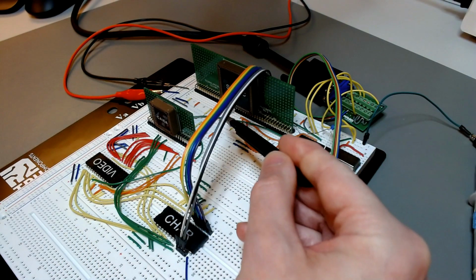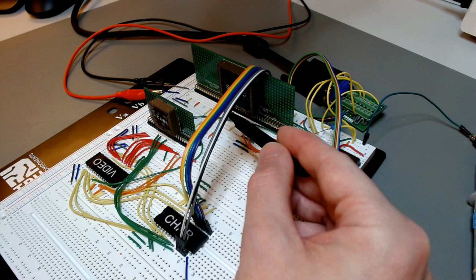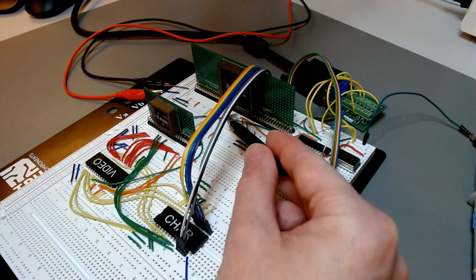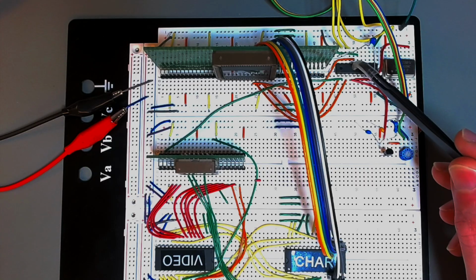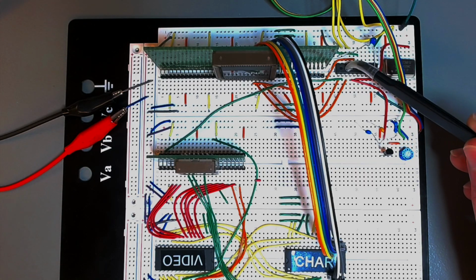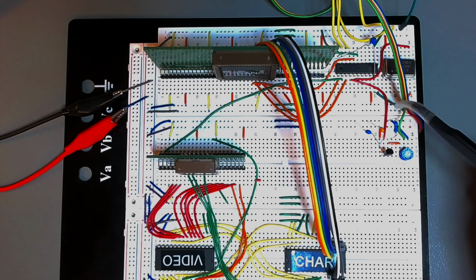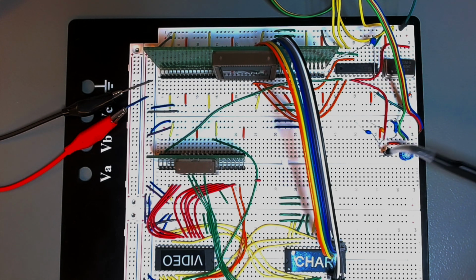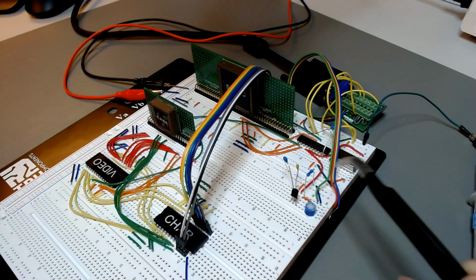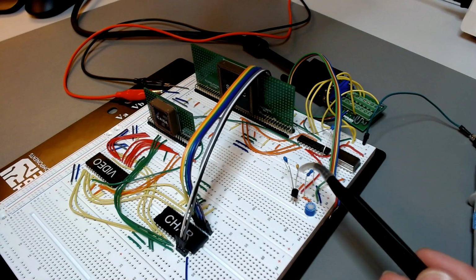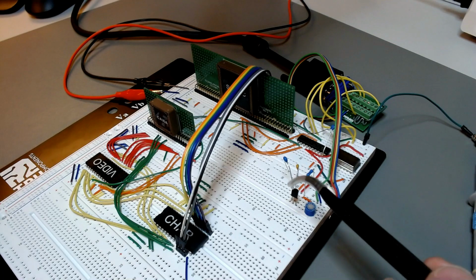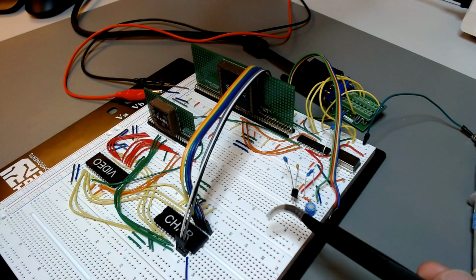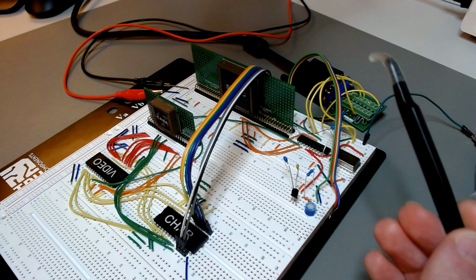Then a byte is produced corresponding to a piece of the character's bitmap, and it goes through these wires into SCANC, and it's loaded in a shift register here in SCANC, and then SCANC will shift them out one by one, bit by bit, through this orange line here, which then goes through the buffer as well to get a little bit more drive, comes out here through this red wire, and then goes through this amplifying transistor, which is to provide even more oomph, more drive to the signal, because my experience has been that it's difficult to drive this connector, the VGA cable, and my monitor, so you need a lot of buffering there. That's why I'm buffering the signal twice.